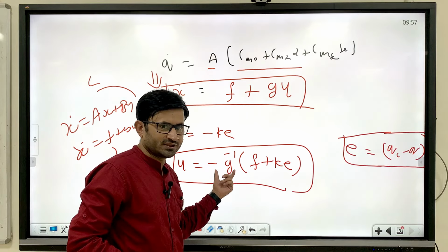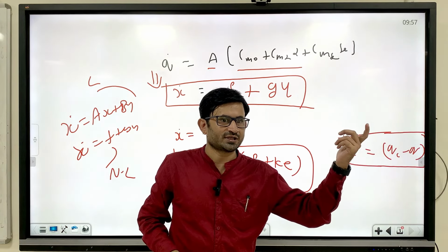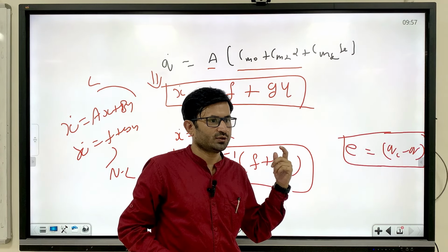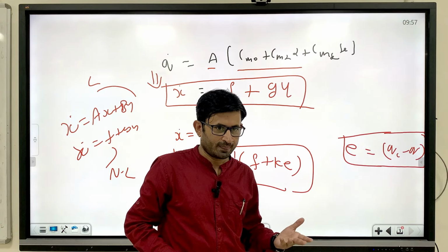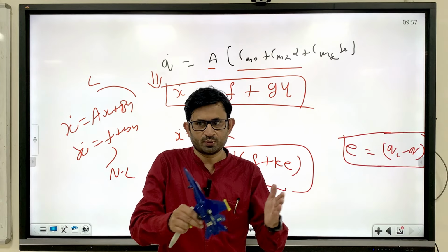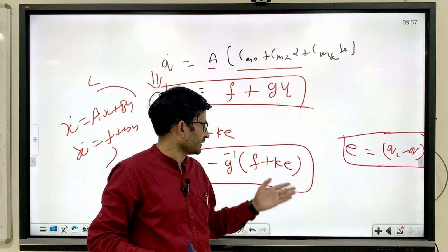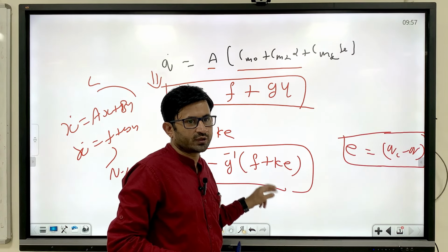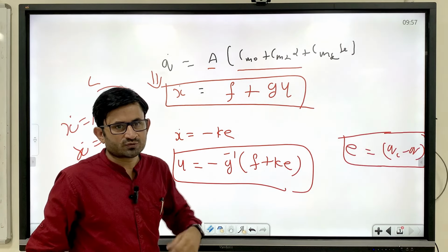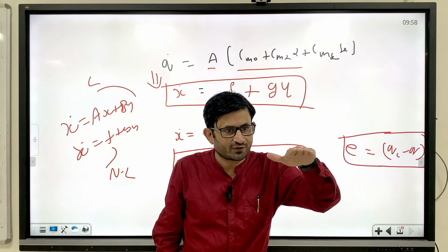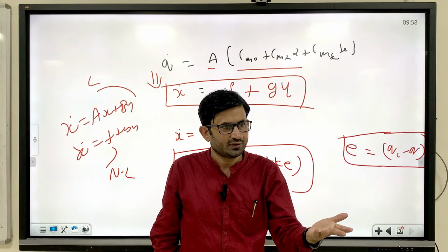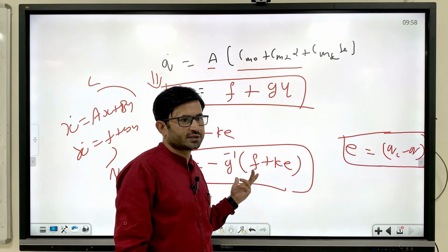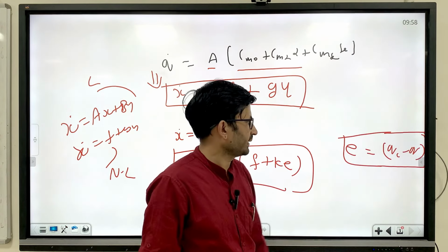You can see this G inverse sitting here, you can say it's a gain. F is also taking part of the gain. So there is no need for gain scheduling. In linear control, you will require many gains when you switch from one trim point to another trim point, because you design the linear controller that way. But when the non-linear part is concerned, this will be automatically computed. For example, see this, x dot equal to ax plus bu. A is the system matrix, calculated for one particular velocity trim point, right? B is also for one trim point. When you change the trim point, this A and B will change. So every time you have to compute the gain, but here it is taking care of G and F. That is what I'm trying to explain.